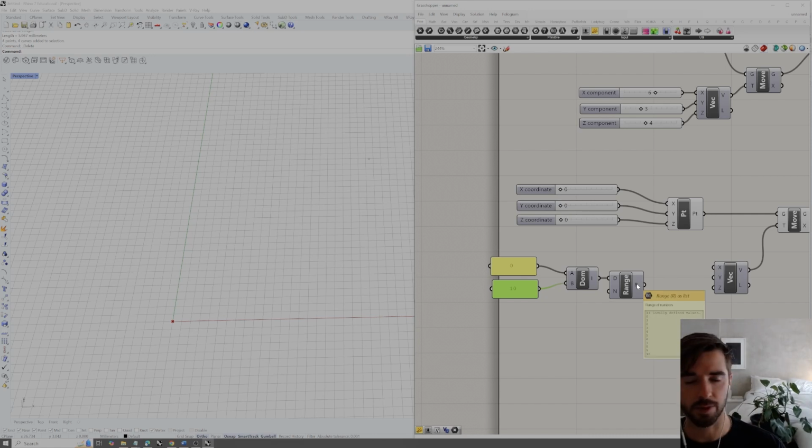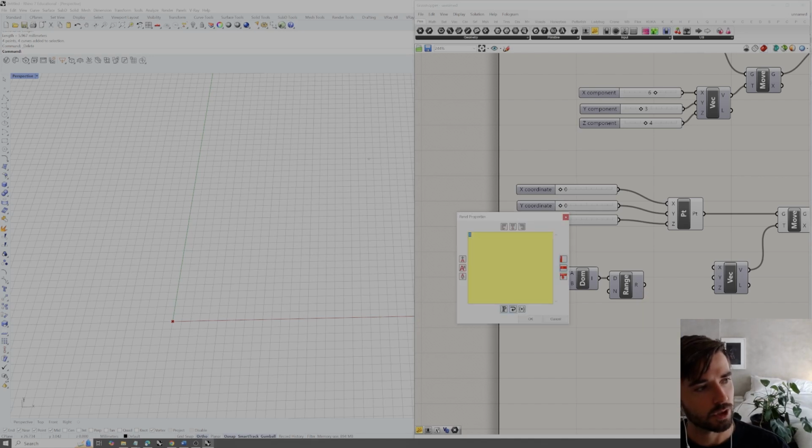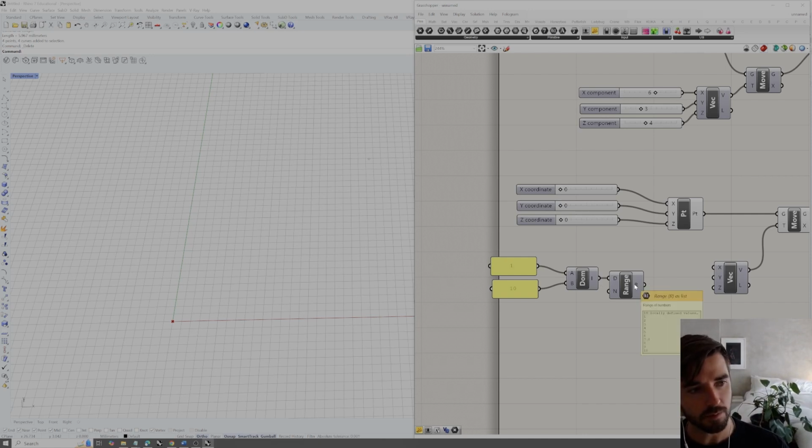If we wanted to change the number of steps that we have here, so instead of going from 0 to 10 with 11 values, if we wanted this to be 1 to 10, then we could change the number of steps here to 9. That's going to make incredibly complex numbers here. So we would need to change our input minimum or start for that domain to 1. So 9 steps, 1 to 10, which is going to give us 10 values, including 1, 2, 3, 4, 5, 6, 7, 8, 9, and 10. If we added 0 to that, that's what gives us the 11th value.